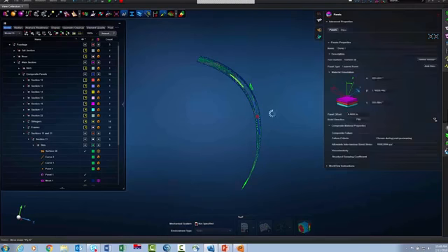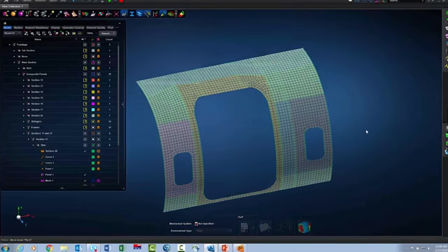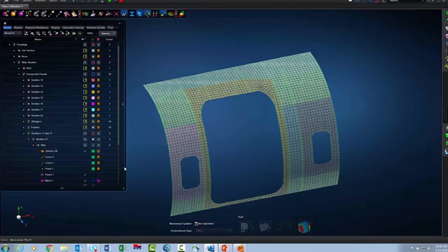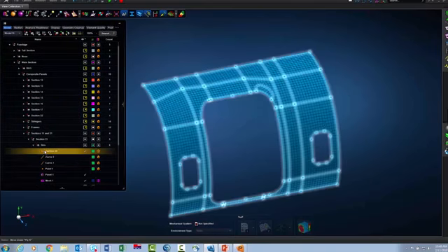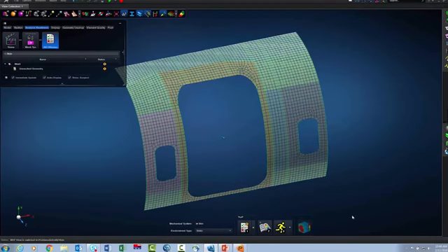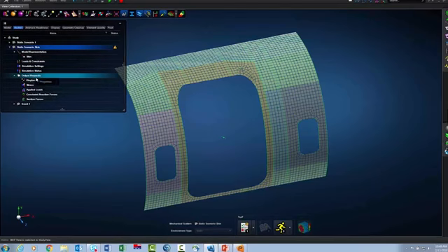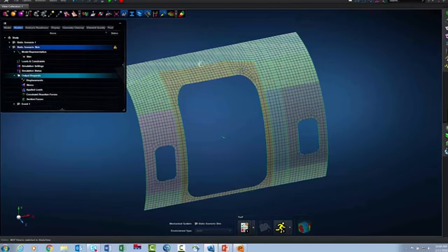So hopefully you see that whether the change is to the layup itself or the mesh or the geometry, all of its composite capabilities in Apex are generative. Let's do an analysis real quick so we can actually do some post-processing. So I'm going to place this in the analysis window, and I'm going to modify my scenario so that I can add strain.